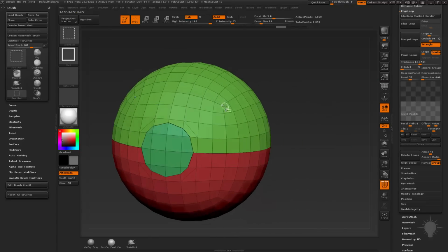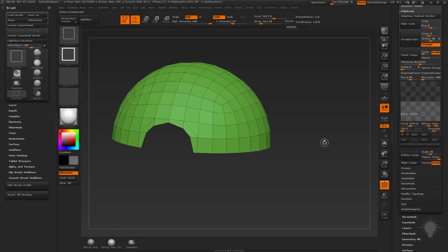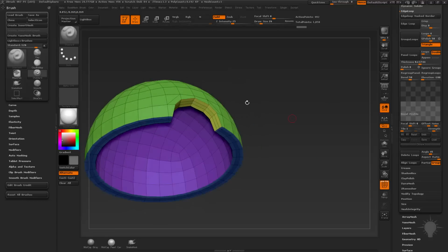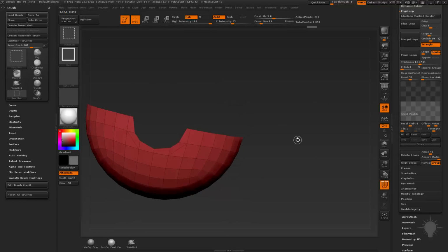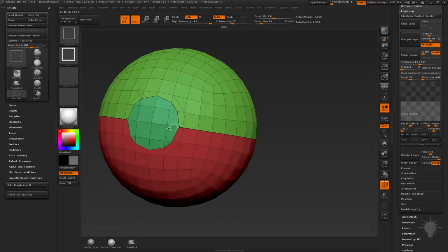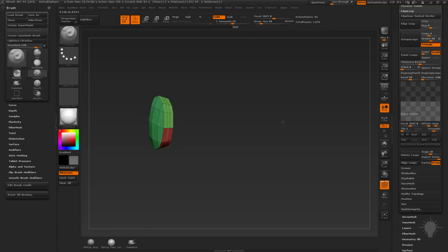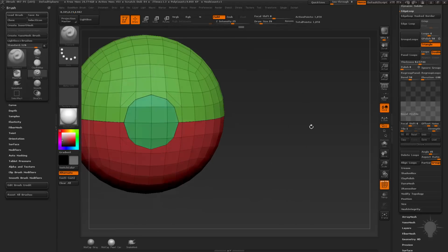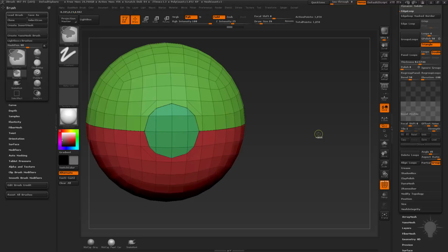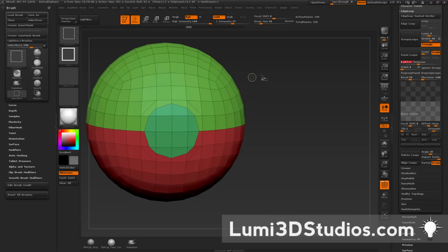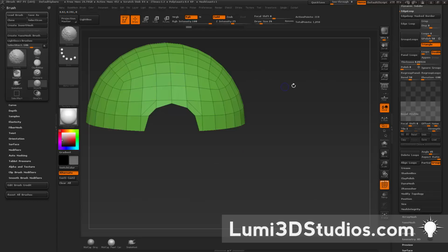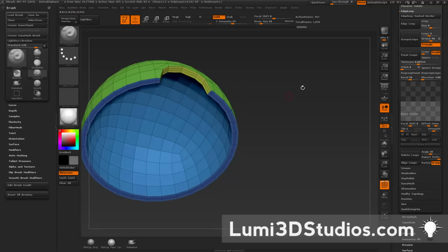However, if I hold down Control Shift and grab one of those shells and then do Control Shift A, you're going to see we have a top piece here, and then grab the bottom piece, Control Shift A, and we have a bottom piece, and then we have Control Shift A, and a middle piece. They're a little bit thick, so I'm going to undo all of that, and then we'll do 0.08, and then hit panel loops, and we'll just test this and see. Control Shift A. There we go. I think this is good enough.